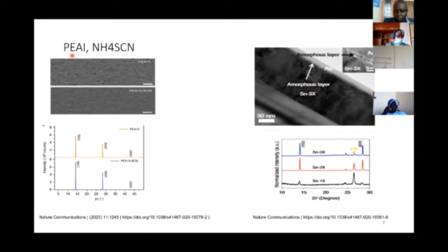And since this is already passivating either the surface or whatever, we are going to have such a film which does not really have grains. It is just there. But the best thing about this film is that the number of pinholes is reduced. And so we are assured that at least the stability of this kind of device will be improved.